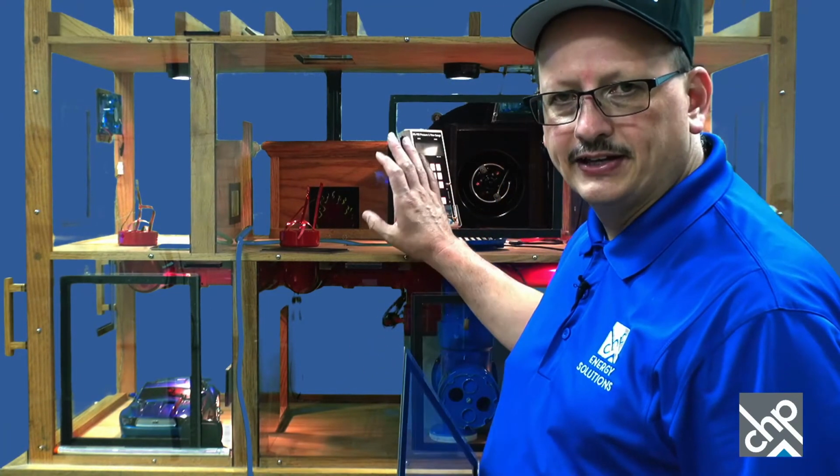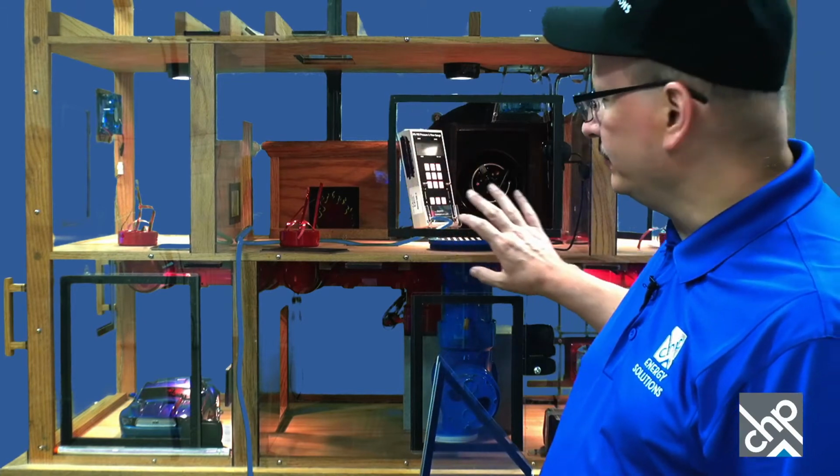But basically, if you've got a combustion appliance that takes air from inside the house, you want to do this CAZ test, which would be like a standard atmospheric water heater, 80% furnace, older 70% furnace, all those items. If you have a 90% sealed combustion, you wouldn't have to do a CAZ test, but you still do your carbon monoxide, your efficiency and temperature rise, and those types of things. But now we're just going to say this is our CAZ up here in the central area of the house.